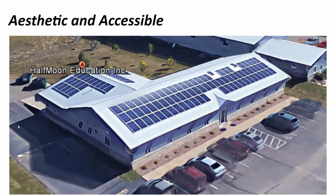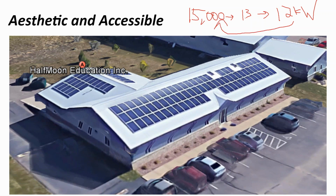For a 2,800 square foot home, obviously it's going to have different electric bills, but on a 3,000 square foot home, depending on the region, depending on if it's all electric or not, let's just assume it's using 15,000 kilowatt hours of electricity a year. And if we know in our area our magic number, let's say you're not in Biloxi where I'm at, 1 to 1.5. Let's say you're further north and you're at 1 to 1.3. So 1 watt produces 1.3 kilowatt hours of electricity a year. And at that point, what I know is I need about a 12 kilowatt solar array to offset 100% of its electric bill.